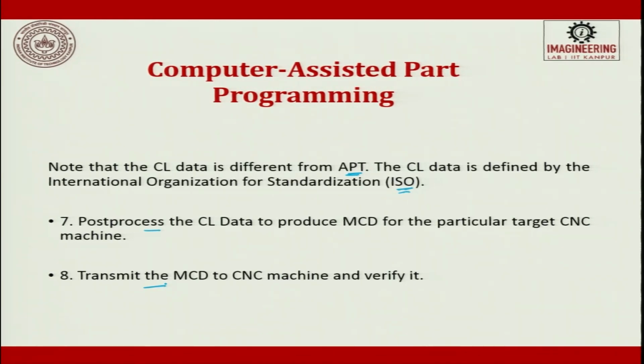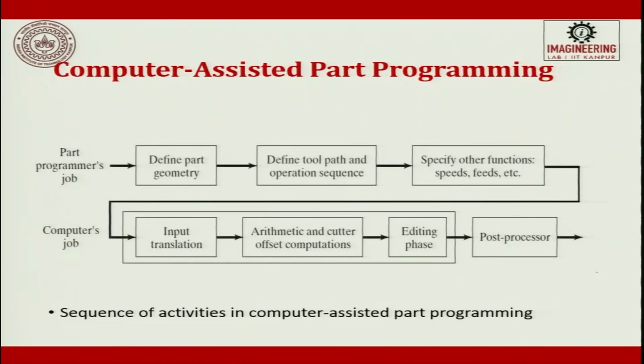So, this is what a part programmer's job is: define part, define tool path operation, specify other functions, speed, feed, etc. The computer's job will be input translation, arithmetic and cutter offset compensation, editing phase and then it does post processing.